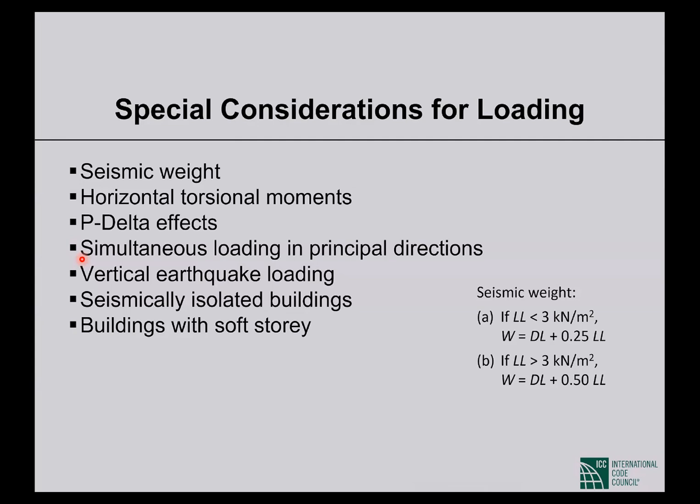In some cases we don't have to, but the way we design our buildings in Bangladesh, in most of the cases, a single vertical member resists loads in both the directions. That's why these simultaneous applications of loading will be required. So this is something new that you have to understand.